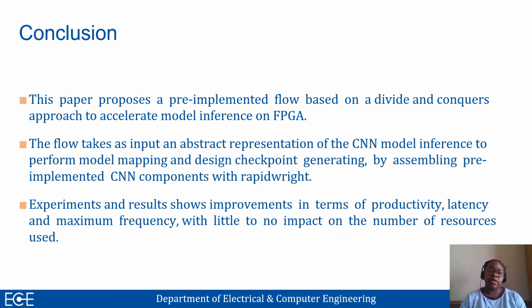So we come to the end of our presentation. In conclusion, we have proposed a pre-implemented flow based on the divide and conquer approach in order to accelerate model inference on FPGA. This flow takes as input an abstract representation of a CNN model inference to perform model mapping and design checkpoint generation by assembling pre-implemented CNN components with RapidWright. Experiments and results show improvement in terms of productivity, latency, and maximum frequency, with little to no impact on the number of resources used.